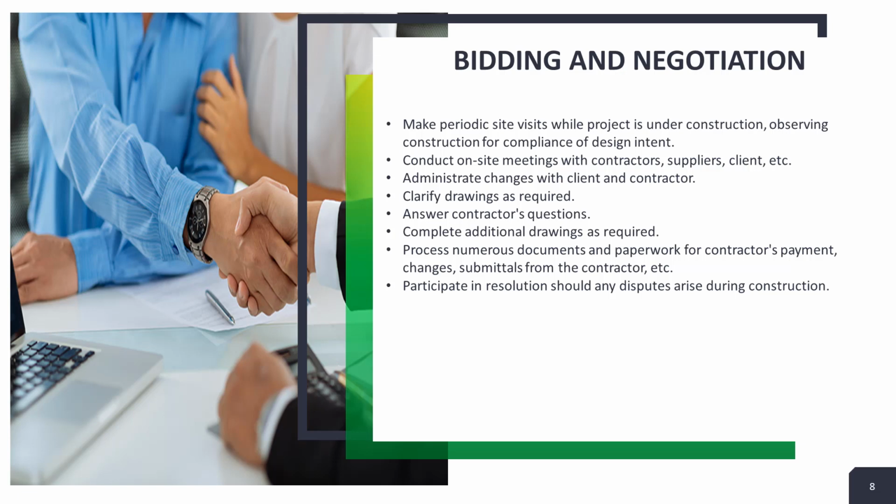Check bidders' qualifications, such as references, insurance, experience, personnel, etc. Provide additional information in the form of addenda to the construction documents as needed to the bidders. During this phase, before the project is bid, any change that is made is included in an addenda. The addenda is an addendum to the documents, either the project manual or the construction documents themselves. After the project is bid, those changes are called other things, which we'll talk about here in a minute.